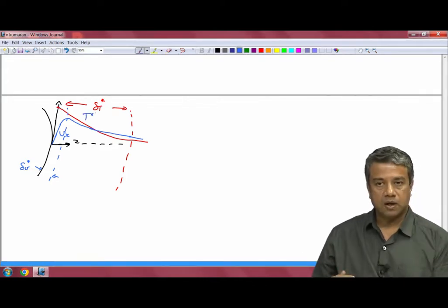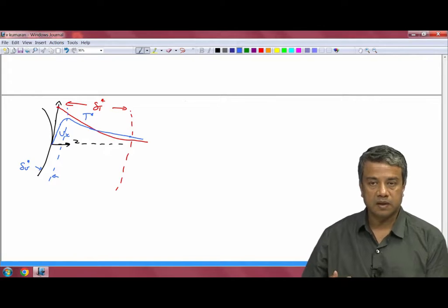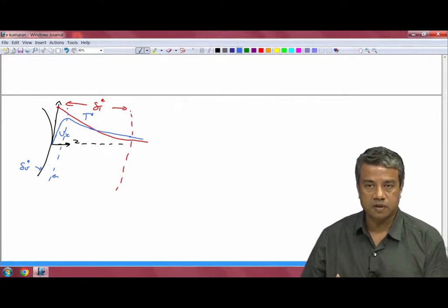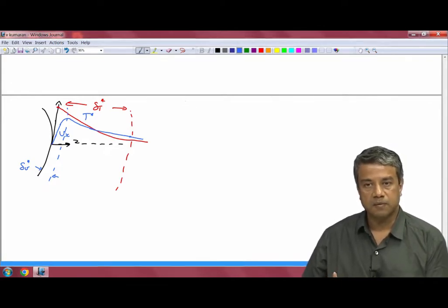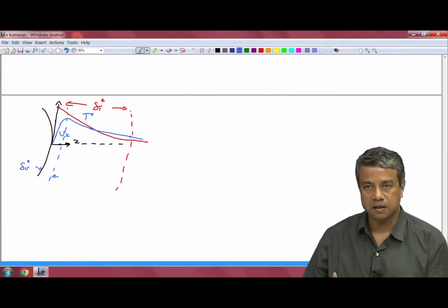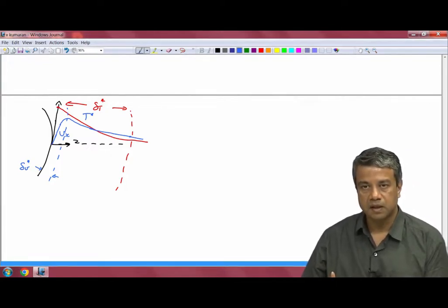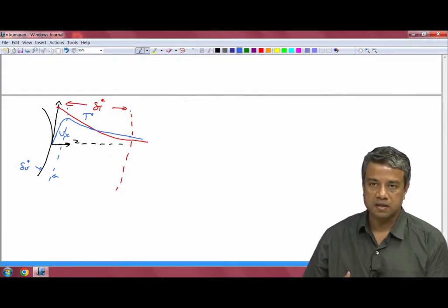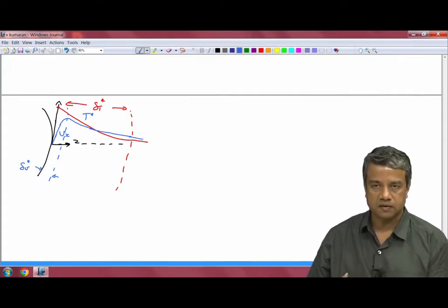Outside of the momentum boundary layer region, momentum diffusion is small, and therefore, there is a balance between the inertial force density and the buoyancy force density. If you neglect diffusion altogether, you cannot satisfy the no slip condition. Therefore, there has to be a correction due to momentum diffusion within this thin momentum boundary layer close to the surface.